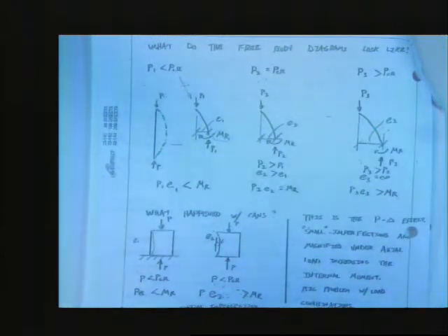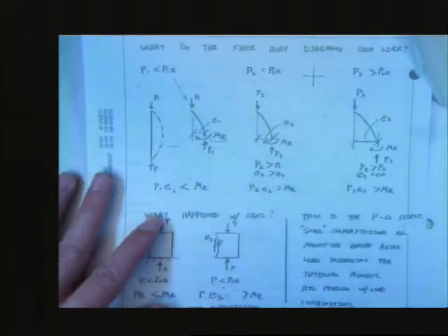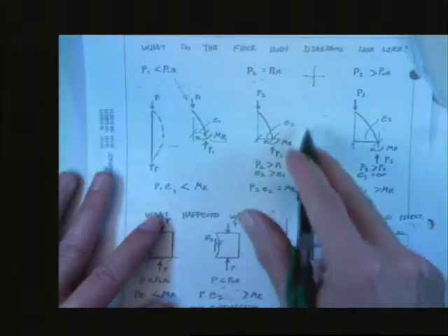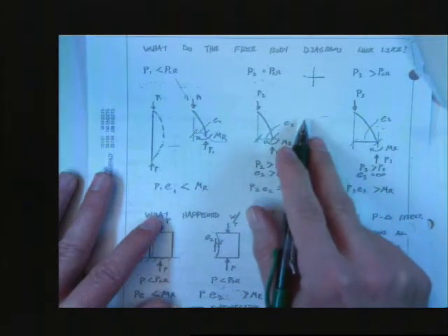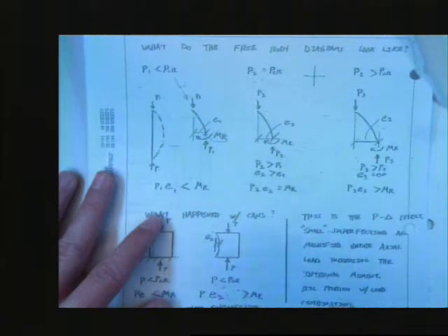Column buckling and lateral torsional buckling. And then there's also other kinds of buckling we don't talk about, like torsional buckling. So instead of things kicking to the side, they just spin. It's weird. The only cross section that does that, though, is a cross. So if you make any Jesus columns, watch out. Like, that's how they fail. They actually fail in torsional buckling. Yeah, they spin. They just spin.